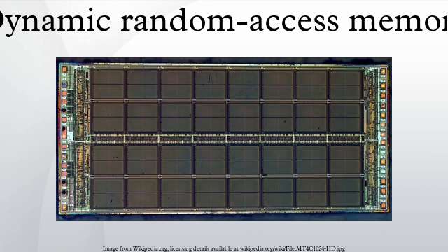Operation principle. DRAM is usually arranged in a rectangular array of charge storage cells consisting of one capacitor and transistor per data bit. The figure to the right shows a simple example with a 4x4 cell matrix. Modern DRAM matrices are many thousands of cells in height and width. The long horizontal lines connecting each row are known as word lines. Each column of cells is composed of 2 bit lines, each connected to every other storage cell in the column. They are generally known as the plus and minus bit lines.